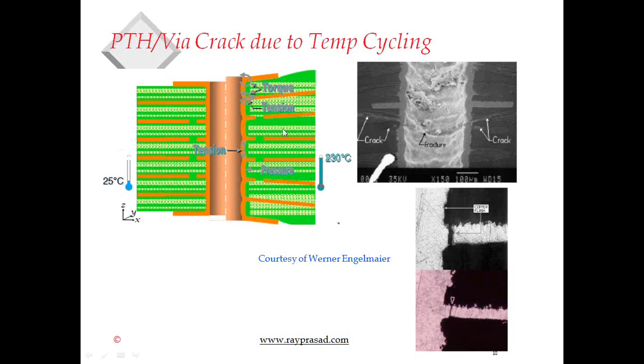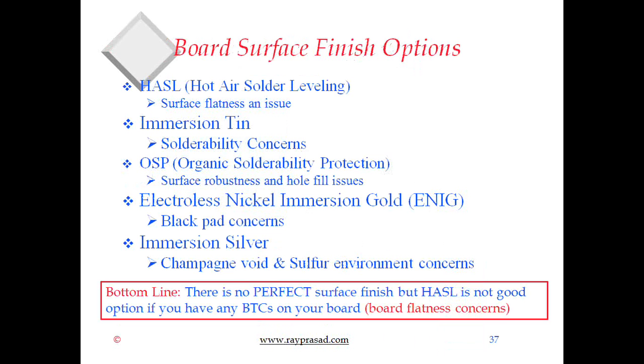So the solution is making sure that you get an epoxy, or excuse me, the resin that goes into the laminate that's intended for lead-free process. All right. The other thing for the lead-free process is the surface finish. Of course, that has to be lead-free, but that has been lead-free for a long time, even before the lead-free came along, because of the flatness requirement.